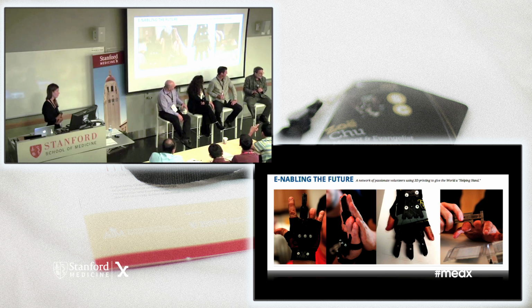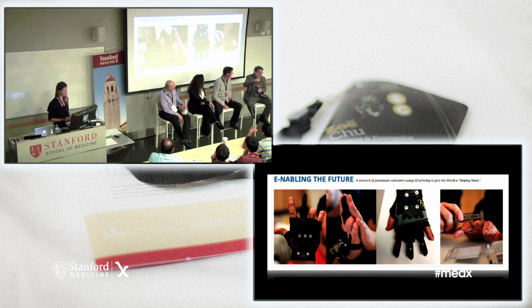Some of you haven't seen 3D printing yet and may not get this, so I hope the rest of you will forgive me while I do a favor to those people. As Scott pointed out, there are a number of different techniques, but if you don't know what a 3D printer looks like or does, first of all, there are some upstairs, but second of all, it may be helpful to know that at least one of the techniques, and the technique that shows up in the $1,000 machines, is basically a glue gun that goes back and forth on a very simple platform, laying down very thin threads of hot glue, which harden, and layer by layer, it then builds up a complicated object like this.